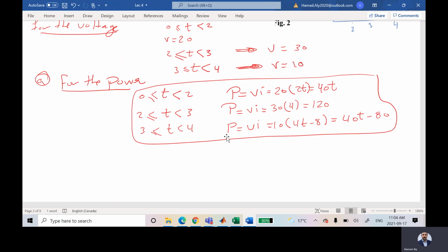Yes. So we had discussed that the energy delivered is the integral of P dt. Supposing it's a circuit with resistive elements, the direction in this example is always positive. In a circuit like the assignment, the current and voltage are positive and negative. But would it be the absolute value of the power? No, the energy is equal to the integral of P dt. It doesn't matter what V is. P is equal to VI. So positive, negative, it doesn't matter for me.